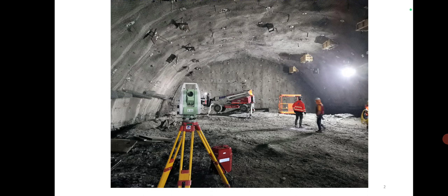In the detailed survey, we collect samples by drilling boreholes, exploratory shafts and pilot tunnels. Boreholes are constructed, and exploratory shafts are vertical shafts constructed to know about the different layers of rocks and their strength aspects. Pilot tunnel construction is also done.